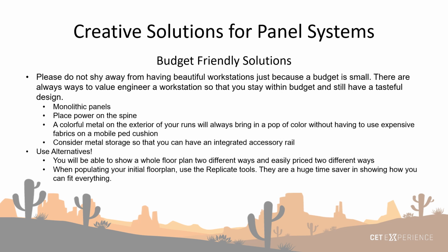Also remember that if you put the power in the wings, it's going to be more expensive. So try to keep the power in the spine and think about how you actually need to lay out your workstations. That way your power can run down the spine only.